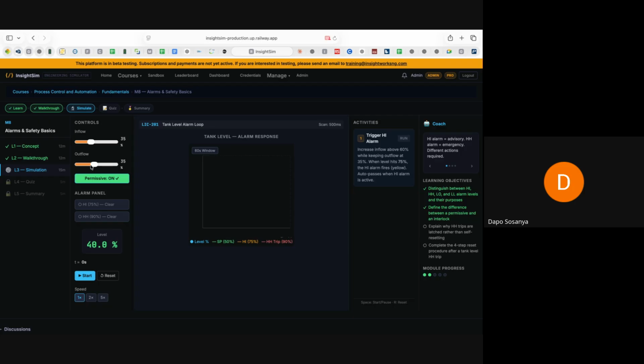So if this is a closed tank, for example, as you have implemented a level measurement in that tank, you probably want to implement a pressure measurement also, so that you can keep an eye on the pressure inside the vessel. So we've measured level, we've measured pressure.